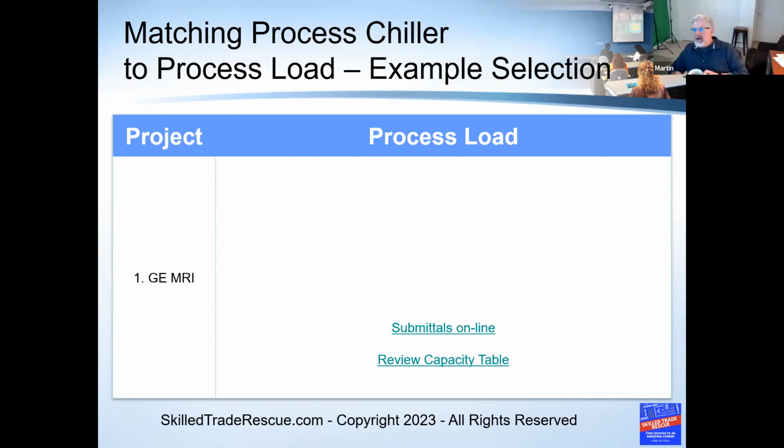Yes, yeah. When we're in the process chiller talking about the fluid side, the hydronic side, when a customer has a 50-degree fluid requirement going into their process, whatever the heck that is, our term for that would be a 50-degree approach. But yeah, I've had more than one refrigeration guy look at me sideways when I say it that way.